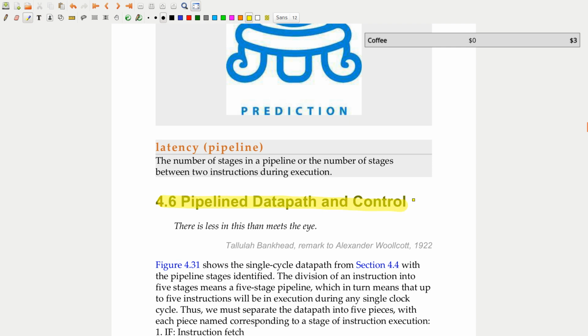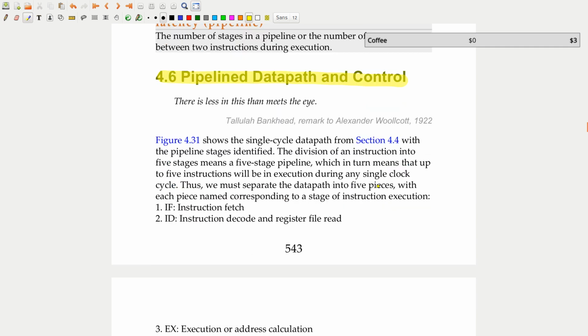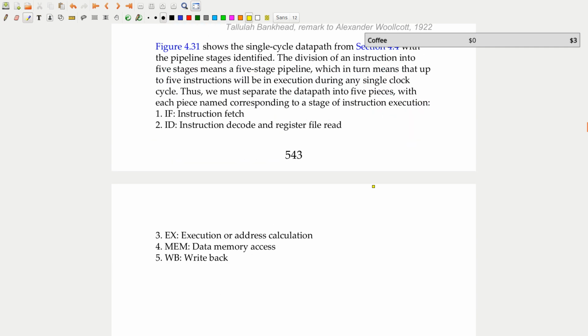We talked about some high-level ideas of how pipelining works. So how would this work in reality with the data path and the control that we were talking about? Like we said earlier, we're going to split the pipeline into 5 stages: a stage for fetching instructions, decoding instructions, executing, memory operations, and write-back operations.